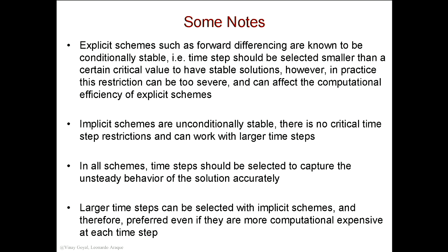That's what conditionally means: I'm putting a condition on my time step. Sometimes explicit schemes can be quite expensive because the time step you have to select is so small to remain conditionally stable.